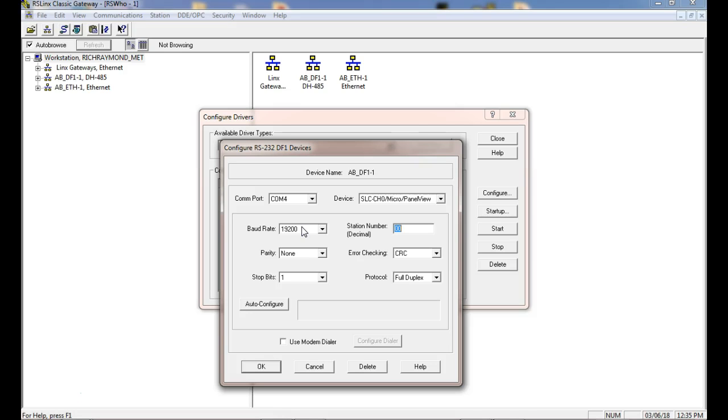If I can combine the two, I can increase the amount of information I send, because not only is my signal changing the amplitude, we can also change the phase. So we have phase shift keying, and this is called quadrature amplitude modulation, which allows us to put more than one bit of information per baud, which is pretty neat.